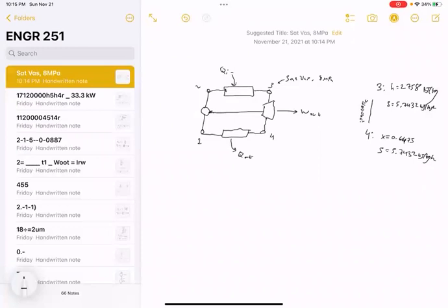Well, remember that we said any heat addition or heat rejection process is isobaric. And that means going from 2 to 3 is isobaric, and going from 4 to 1 is isobaric. Now, if 4 to 1 is isobaric, that means if we know the pressure at 1, we know the pressure at 4. And if we know the pressure and the quality at 4, then it's much easier to find out what the enthalpy is, right? So let me go back to the actual question and reopen it.